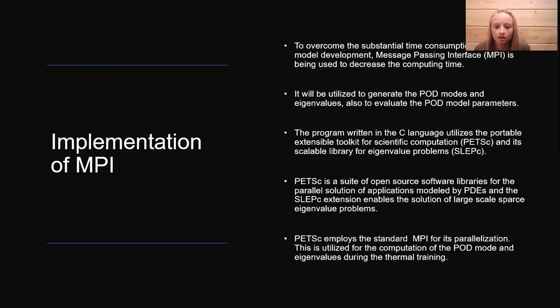PETSc is a suite of open source software libraries for the parallel solution of applications modeled by PDEs, and the SLEPc extension enables the solution of large-scale sparse eigenvalue problems. PETSc employs a standard MPI for its parallelization. This is utilized for the computation of POD modes and eigenvalues during the thermal training.